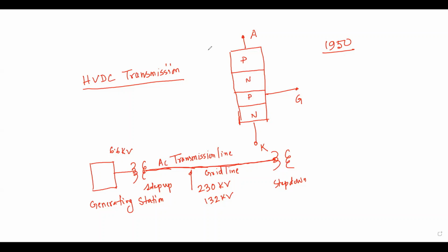Sir, because in a step up transformer, the voltage steps up but the current steps down. So if this power is P1 and here is P2, if it is lossless, then P1 must equal P2, so V1 I1 must equal V2 I2.